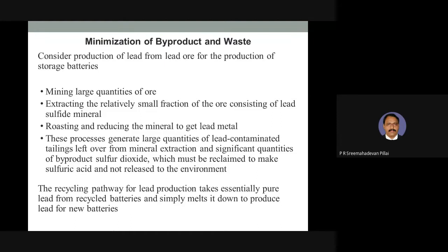So like that, when boiling a metal or its ore or scrap in an induction furnace, you'll get thick scum on top of the furnace. But that scum is a mix of so many things, so it has to be thrown away. But nowadays that scum is being reused, because it is known by the technical term slag. Slag is being powdered and used as an additive in cement manufacture, and you get slag cement.